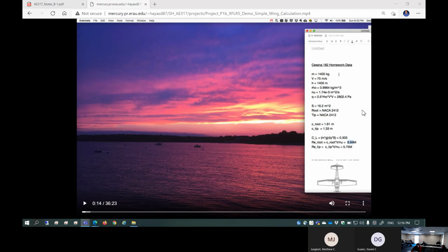So you have to understand, you have to cover the Reynolds number of the wing by, first of all, developing your database. Database is a 2D airfoil cross-section, in this case, NACA 2412. So before you do wing design, you have to run 2D airfoil simulation of NACA 2412, which covers this Reynolds number range well enough so that using that database, you can design your wing, okay? So let's just move on.